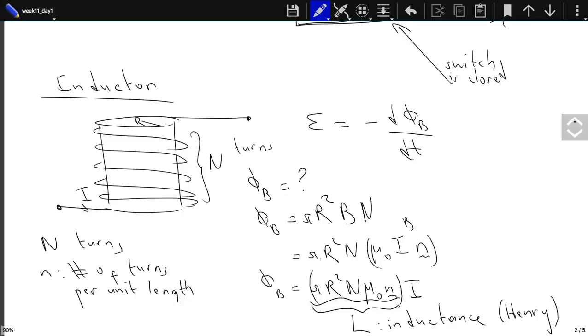If we just connect the capacitor to a circuit initially with zero charge, it just acts as if it is not there. But if the current runs long enough that the capacitor will be fully charged, after that it just acts as if it's an open circuit. It doesn't allow the current to flow after some time. So those are the two extremes of a capacitor. Initially, without any charge, it acts like a short circuit. Fully charged, it acts like an open circuit.